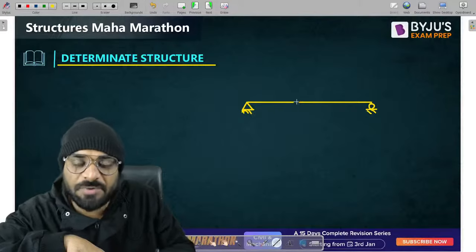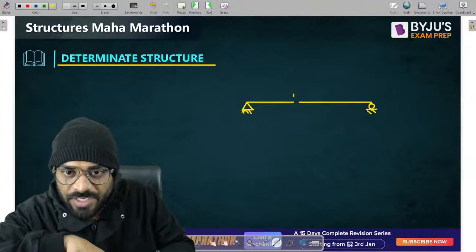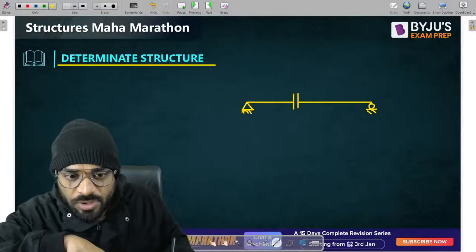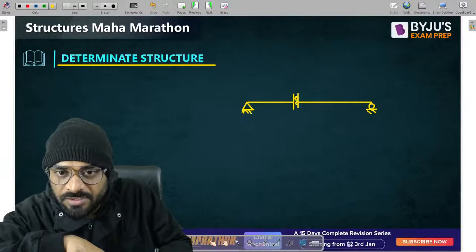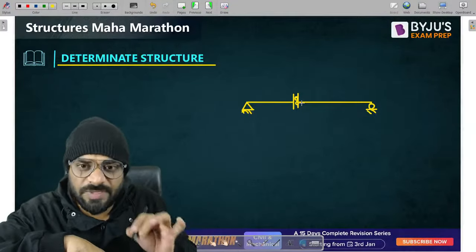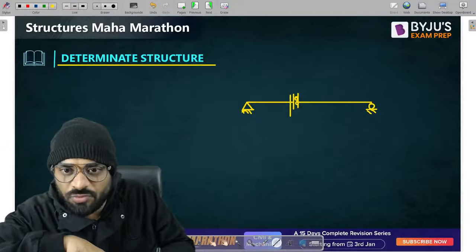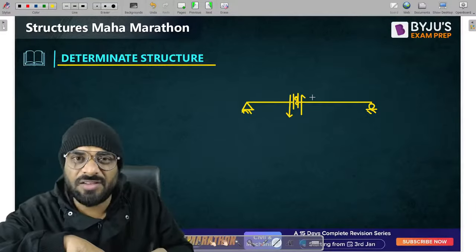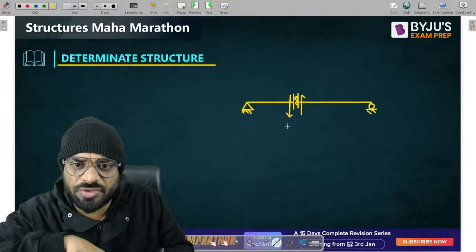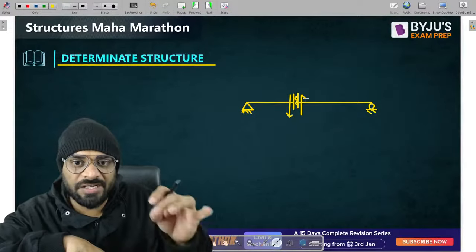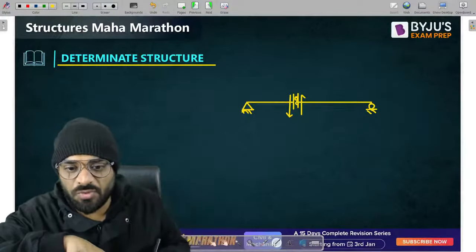If you release that particular reaction, that means we need to use guided roller, right? And the net unit displacement which we have to give is 1. So you know that guys, this left portion moves downward, right portion should move upward. Why? Because we have the shear force on this particular part also. And the net displacement is equal to how much? That should be equal to 1.